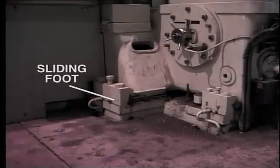The reverse situation occurs during a shutdown. In this case, the rotor contracts much more rapidly than the shell, and as a consequence will reduce the differential expansion and generally move into the negative zone. Normally, the manufacturer sets limits of differential expansion for both the negative and positive sides. The expansion position of the governor pedestal is also indicated.